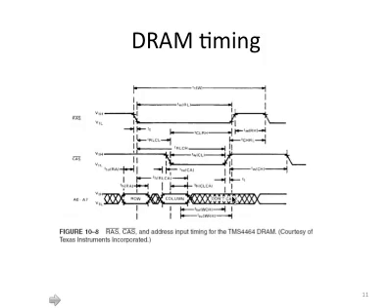And once that's done, after a certain time, this memory access will complete. Because the chip has both the row address and the column address internally, together it has the 16-bit address it needs to access the data.